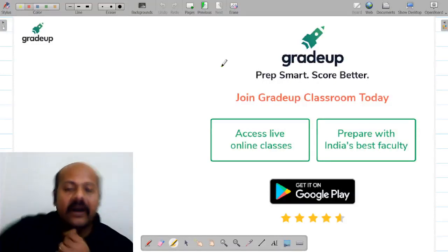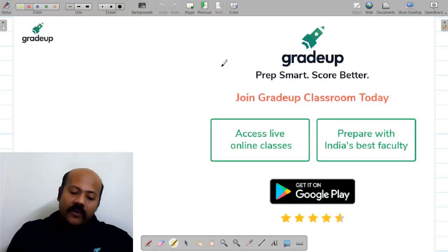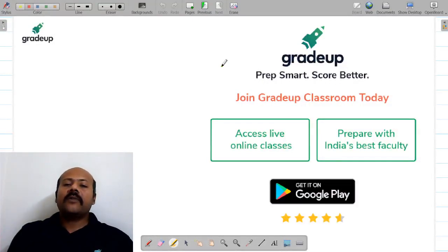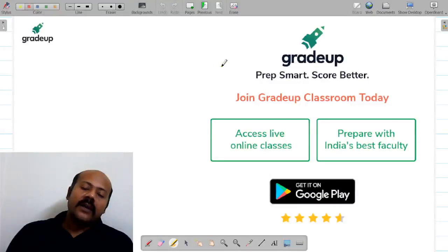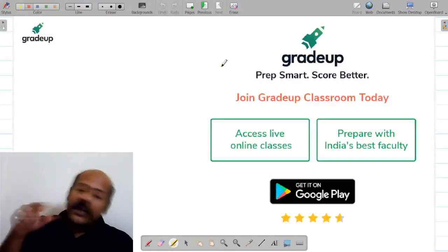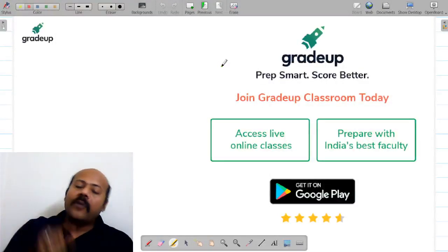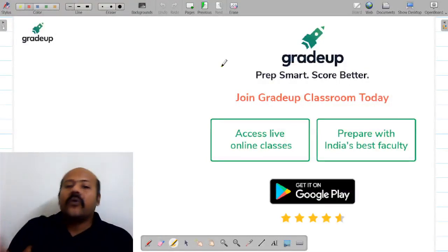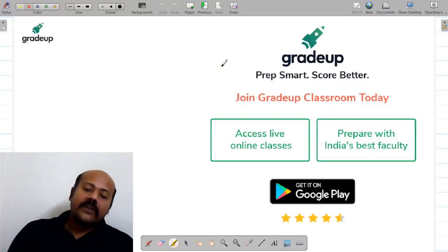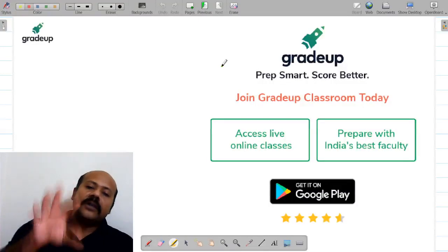Yes, Gonda Kavya, in general, this is going to be the formula. Let me tell you that this is the voltage regulation formula we normally use everywhere. This is a modern convention. The old convention is E2 minus V2 upon E2. Some of the textbooks follow that old convention, but the modern convention is to represent the voltage regulation in terms of full load.